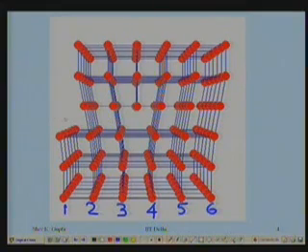This is the plane where I had cut the bonds, and this one got pushed to the third one. Number 2 got pushed from the top to the third one, but the third one does not get pushed to the fourth one because this bond is not cut, and therefore this plane hangs here and is unable to form the bond there. I have formed a part plane in the crystal by this technique. Alright, and this is the configuration of an edge dislocation.